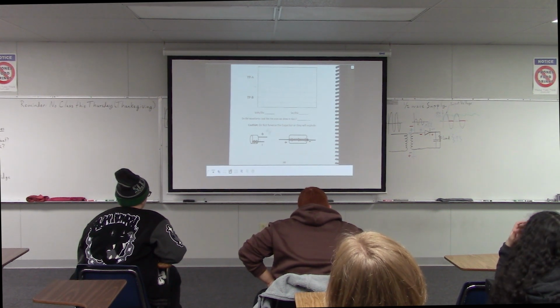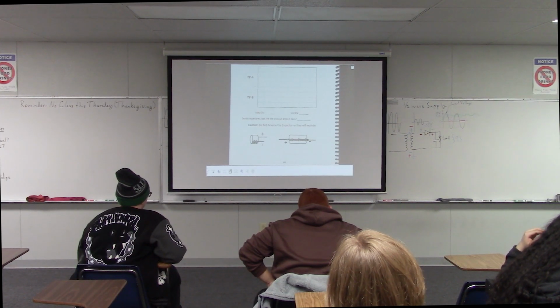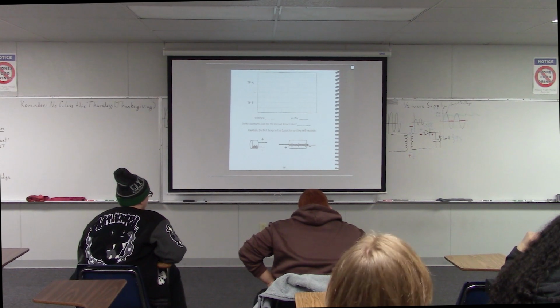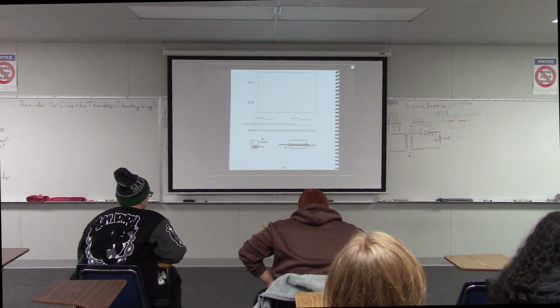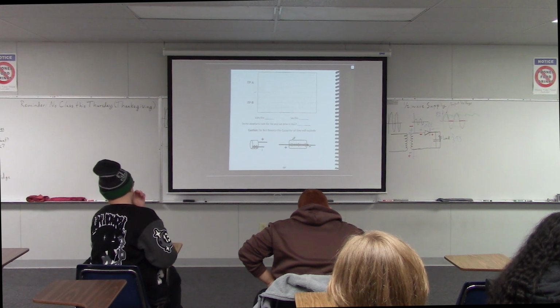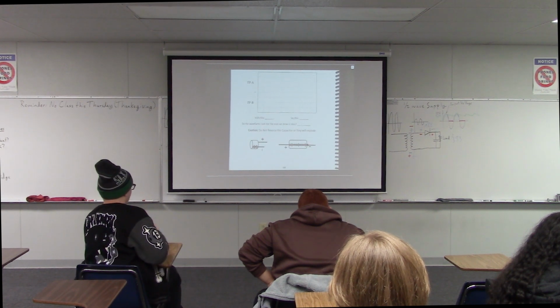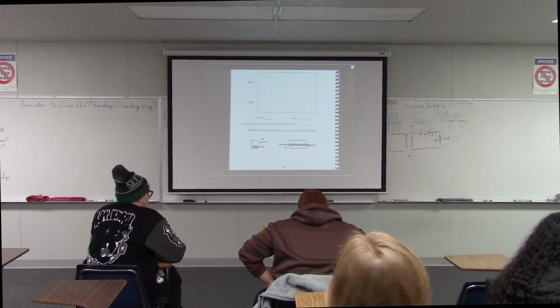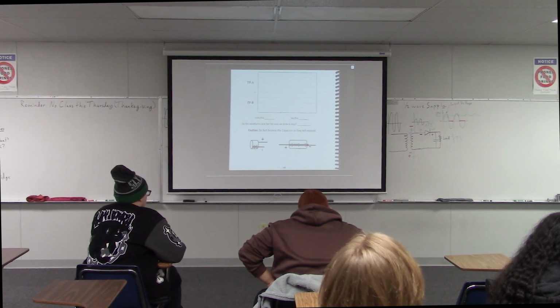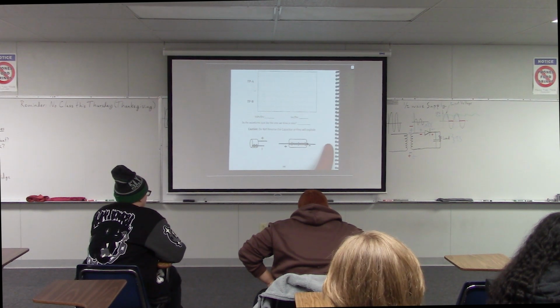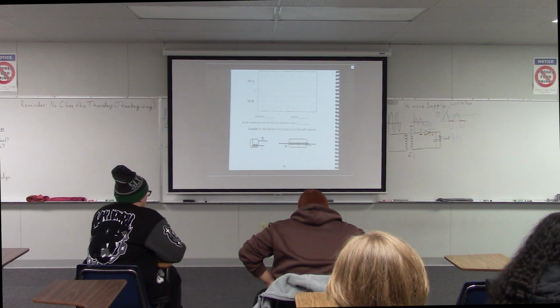This is a reminder that electrolytic capacitors are polarized, so you have to pay attention. This is a circuit where your capacitor will blow up if you plug it in backwards. Okay? We're using higher voltages and higher currents here, so this capacitor will explode if you plug it in backwards. So this is a time when you really have to be extra careful when you're plugging these in. Please pay attention to the direction where you're plugging in your capacitor. This reminds you which side is positive and negative on a capacitor.